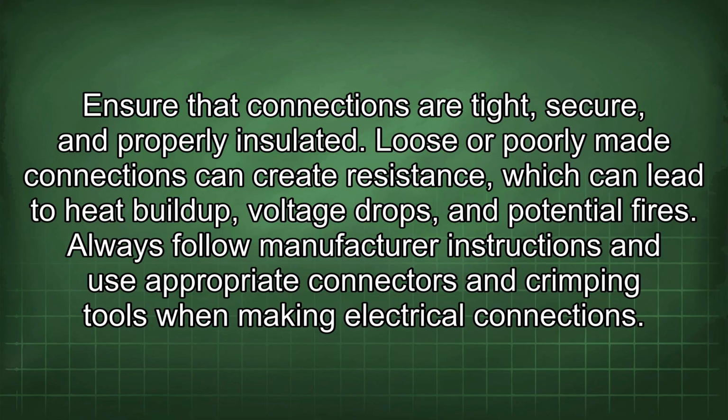Loose or poorly made connections can create resistance, which can lead to heat buildup, voltage drops, and potential fires. Always follow manufacturer instructions and use appropriate connectors and crimping tools when making electrical connections.